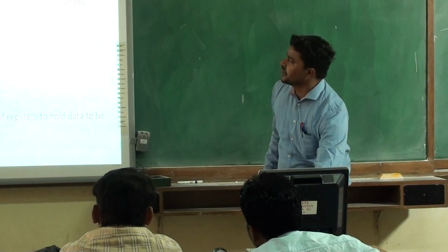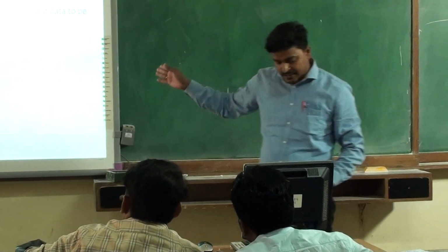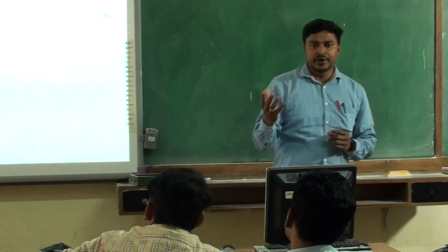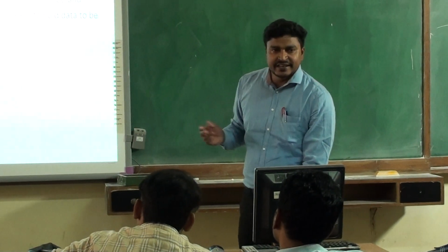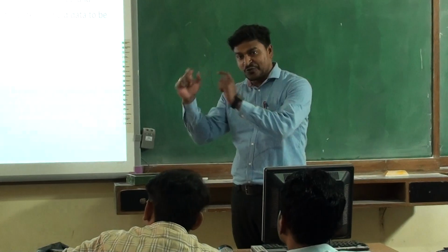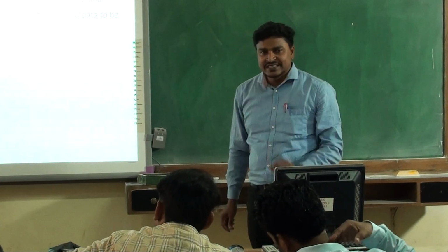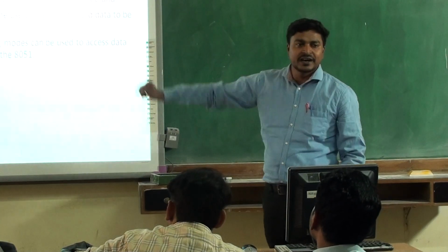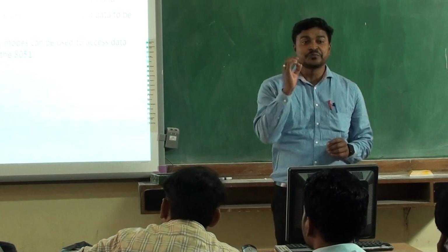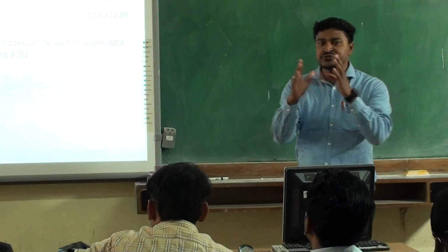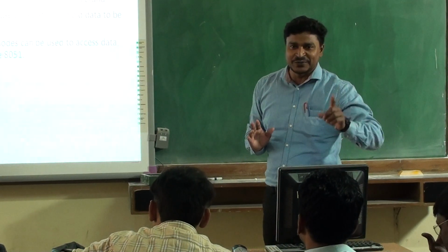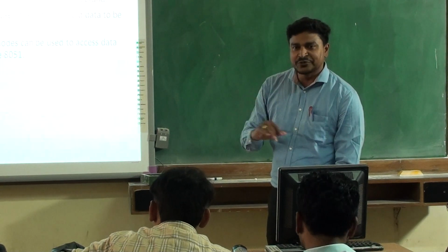So this is the summary. We have summarized all the addressing modes. In immediate, we learned how we transfer immediate data. In direct, we learned how from some location we transfer the data to a specific register. We also said that register indirect mode is used as a pointer, which is the best thing, because a pointer is a very powerful thing to use in a microcontroller.